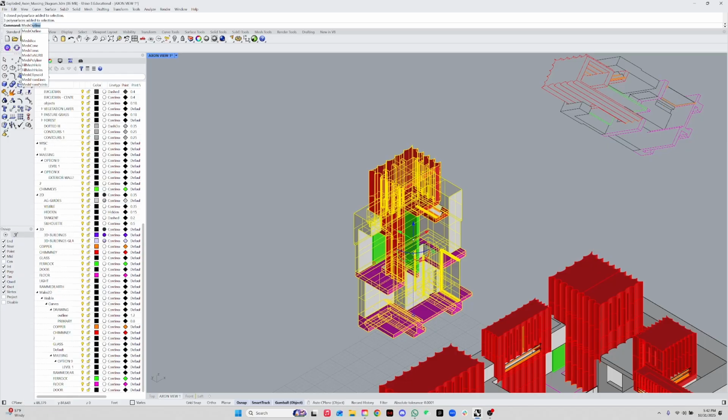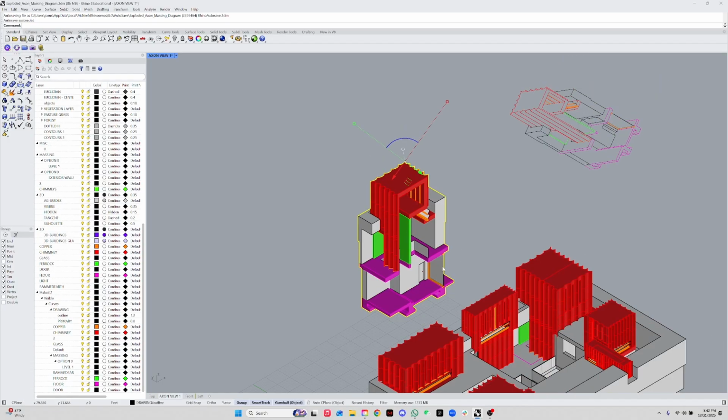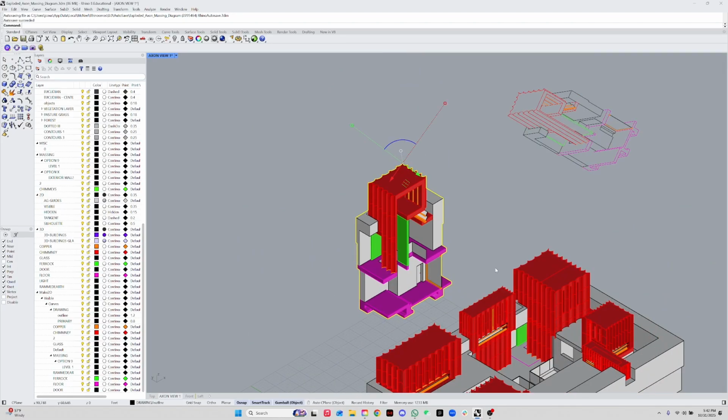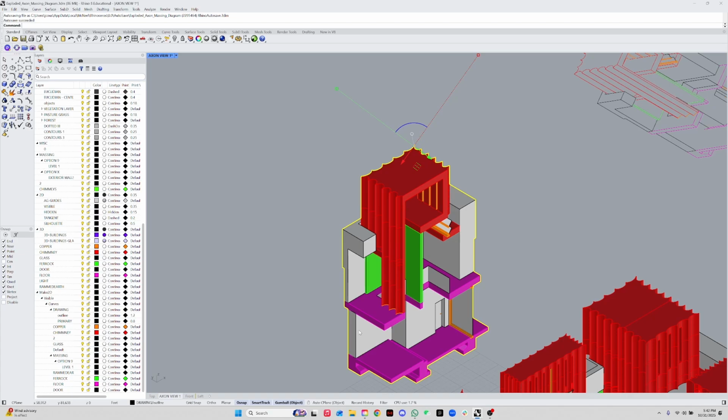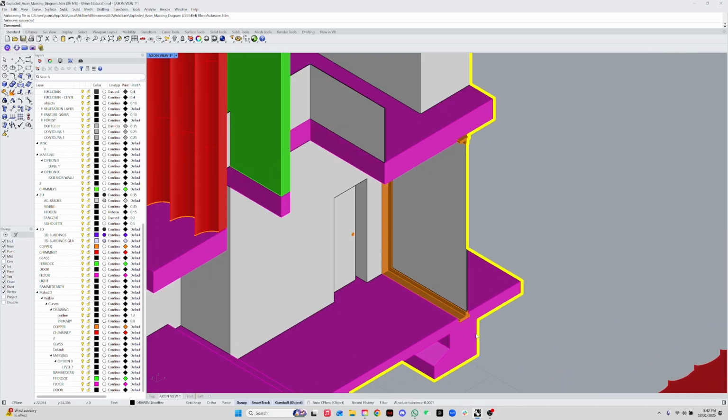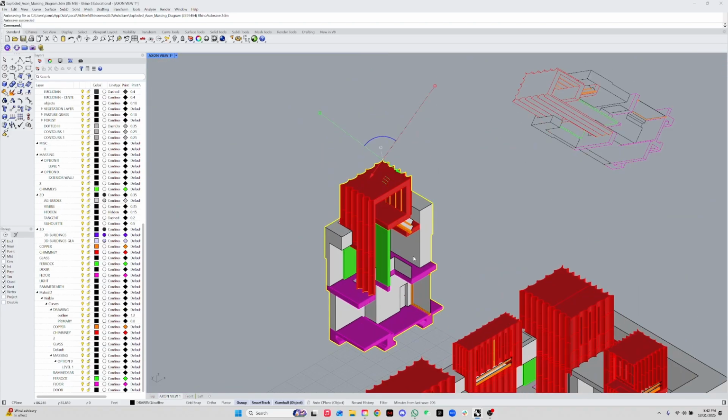And these are just little tricks for you to know, in case you're not getting a mesh outline. And then there you go, I got my mesh outline. So it didn't work when I picked the whole model, but for some reason it does work when I pick my edges only. So just pick your outer boundaries on your model, like just pick the poly surfaces, and then make sure that you select those, so then when you do the mesh outline, it comes out nice.